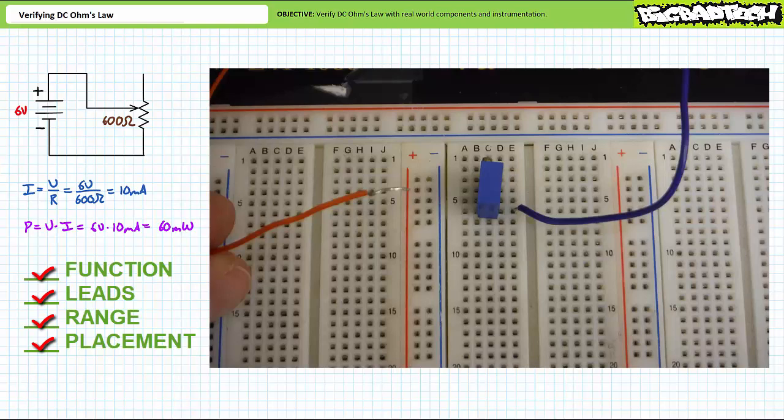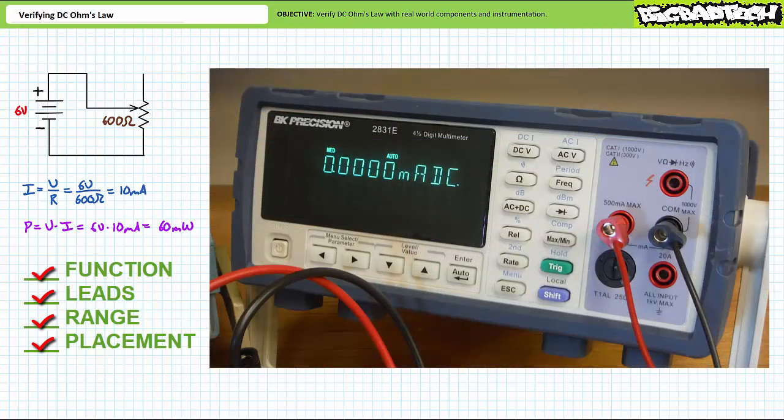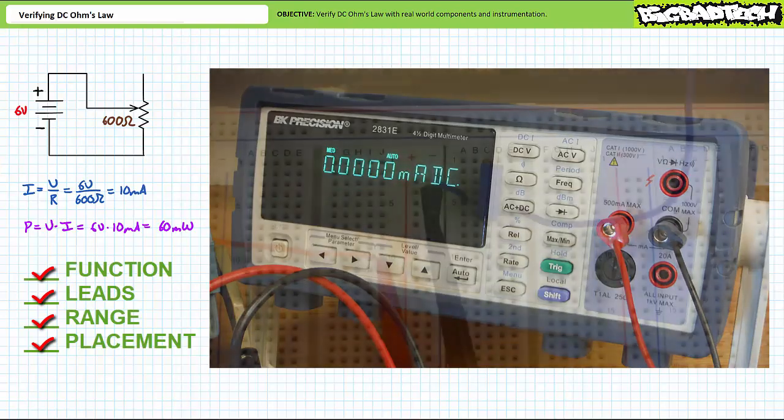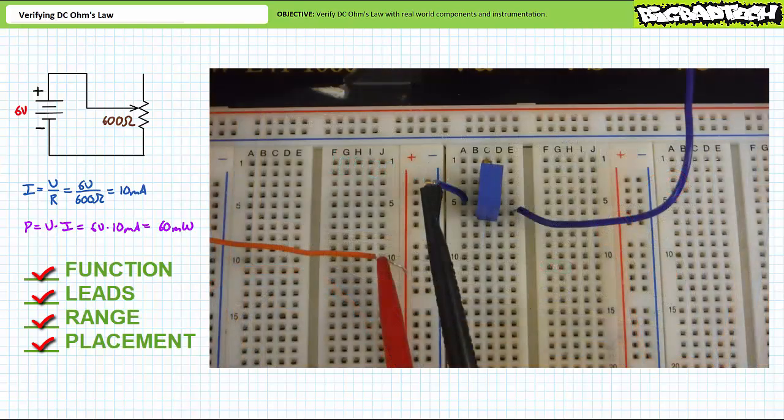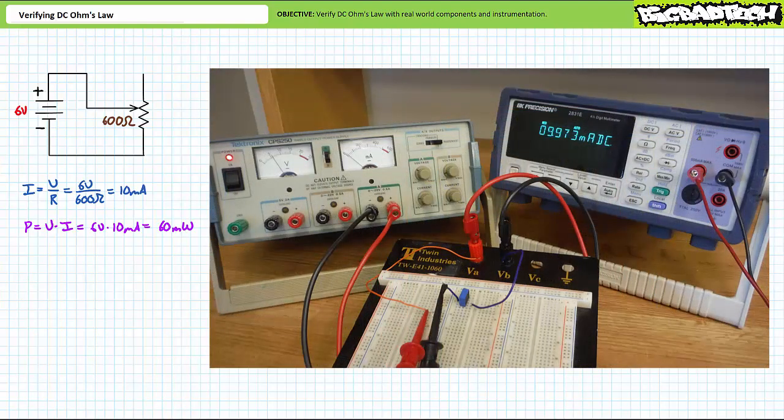Now insert the ammeter to bridge the open such that all current must pass through the ammeter. Out of the power supply positive terminal into the ammeter in door. Through the ammeter. Out of the ammeter out door. Into the potentiometer middle terminal landed at node 5A through E. Through a portion of the potentiometer. Out of the potentiometer at node 6A through E. And into the power supply negative terminal. A complete circuit has been established and all current will pass through the ammeter. When we turn on the power supply, the ammeter demonstrates current through the circuit is indeed consistent with our theoretical calculations.